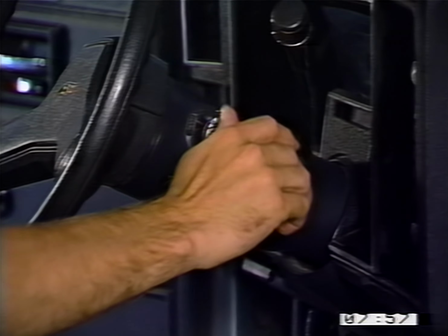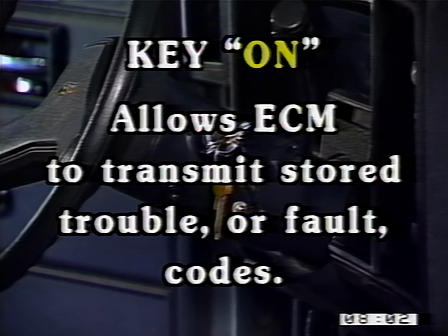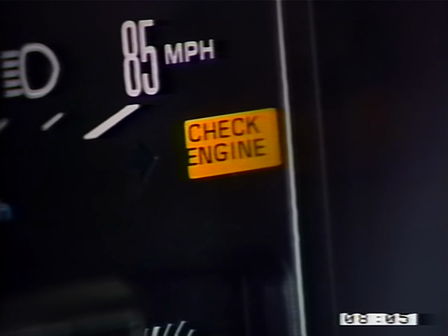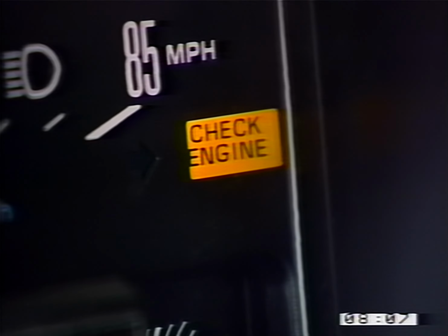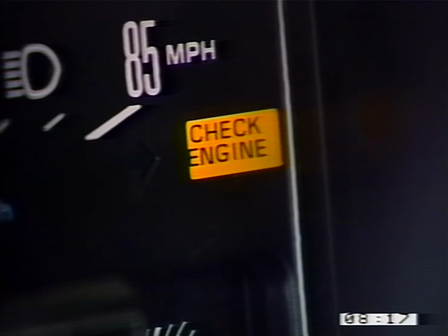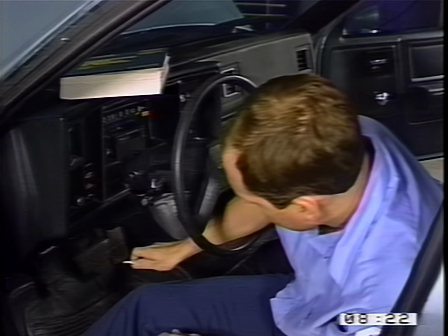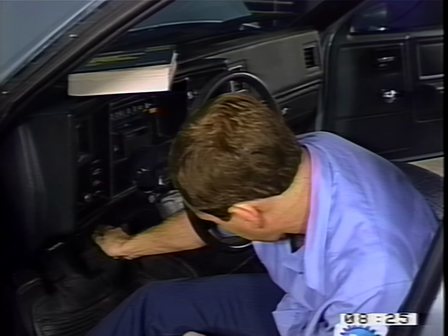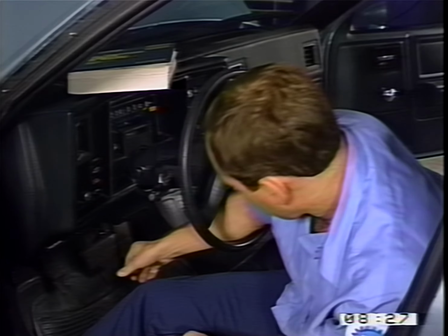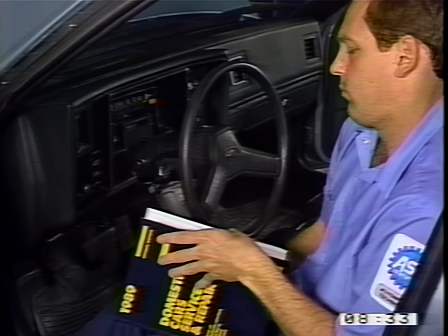Turning the key on after grounding almost all C3 versions allows the system's ECM to transmit stored trouble or fault codes. The stored trouble codes are displayed as a series of 1 to 2 second flashes. Codes flash 3 times in sets of 3, beginning with stored code 12, and continue upward until the last one is displayed. A code 12 should always be present when the engine is not running. If a code 12 is not being displayed, the tech proceeds to the No Code 12 diagnostic procedure, which will determine if there is an ECM or PROM problem.